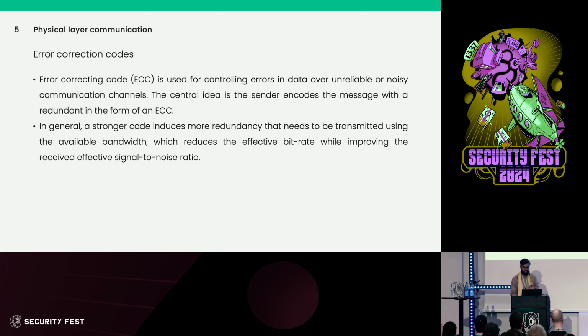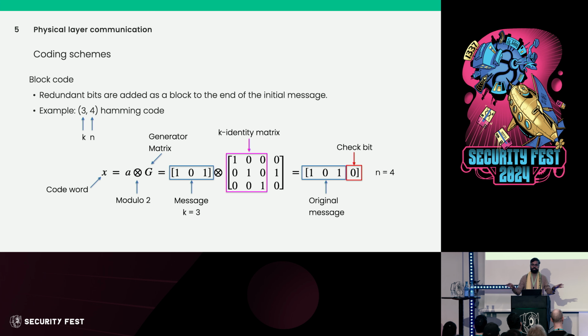These three things are done by error correction codes, and again, there are a bunch of simple looking to very strange looking mathematical things which allow us to do it. We will not go into nitty-gritty of that. You just need to know that there are basically two types. One is block-based code, where you need some block of data. And then you put error correcting code for that entire block.